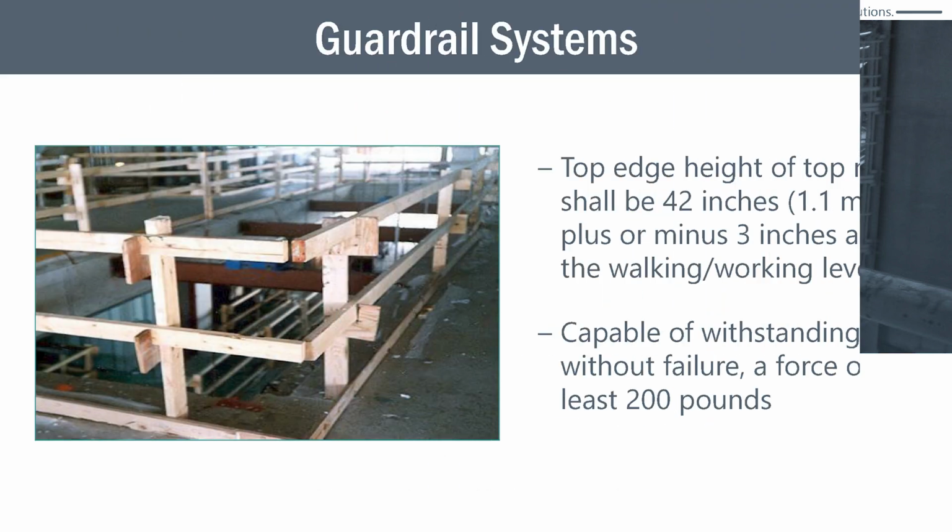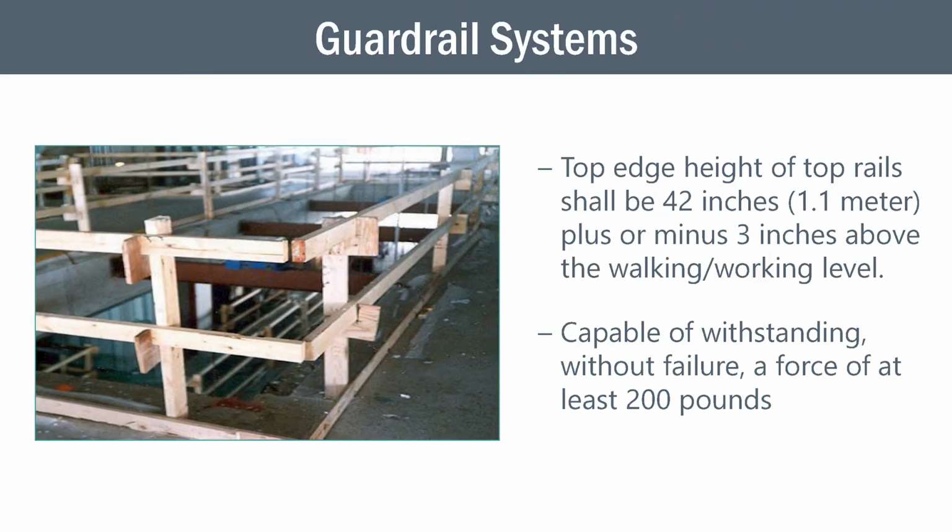One of the bigger ones that I see out there in the field doing audits is having guardrails. And are they high enough? They should be at least 42 inches high, depending upon what it's made out of. If you've got a chain, you've got a little bit of leeway there, but you have to worry about the sag in the chain. Okay. But also, can the handrail support a force of at least 200 pounds applied against it?